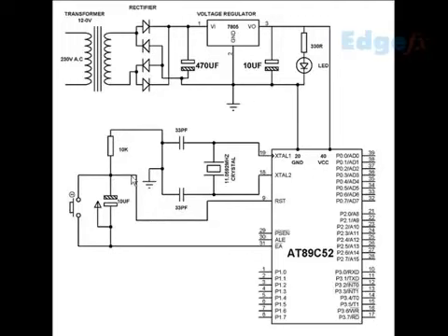So initially at the time of switch on, this point goes high. After that it goes to ground, that is negative. That is necessary for the program which is written here to start from the beginning. Otherwise the program may start from somewhere halfway through. To ensure that the program starts from the beginning, this arrangement, the reset arrangement, has been made, which is a very standard connection for all the microcontrollers.